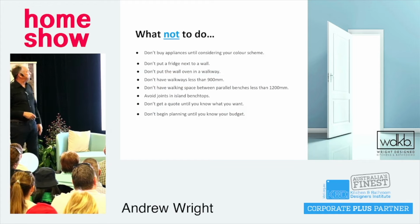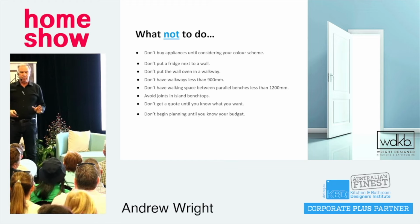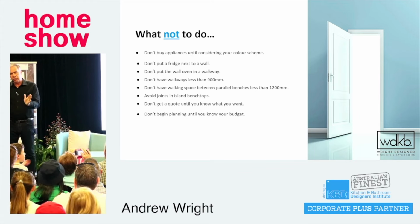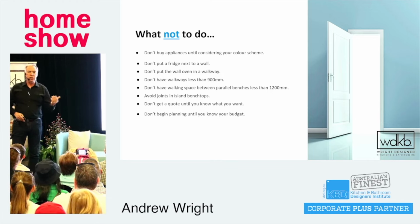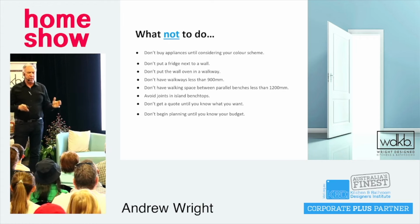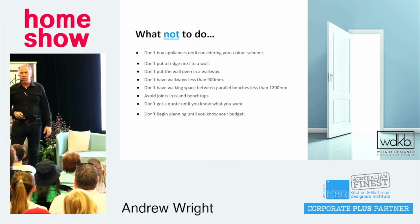What not to do? Don't put a fridge next to the wall, particularly a double door fridge. With a single door fridge, the shelves probably won't be as deep, although on modern single door fridges the shelves are quite deep. But with a double door fridge, the shelves are very deep. When you open the door, if you can't open it to 170 degrees, you won't be able to pull out the meat trays. You won't be able to pull out the veggie trays, all that sort of thing. So you must have at least 250 to 300 millimetres on either side of the fridge, so you can open the fridge and get easy access to all the items inside.